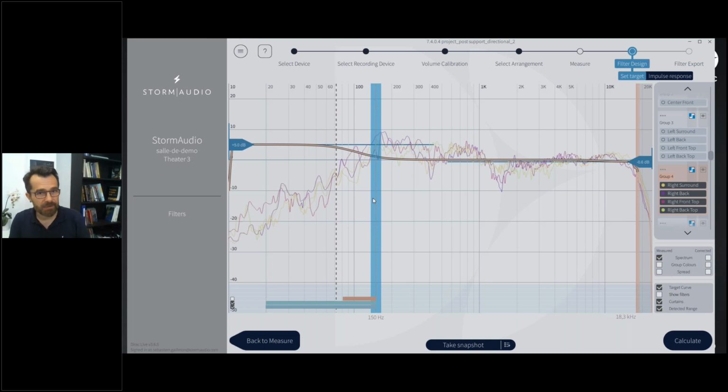But it can also create a very nice result by keeping the bass that is coming from the side speakers on the sidewall. Especially with new codecs like Dolby Atmos, you will get a lot of low frequency content coming from there, not only because of the LFE, but also because those speakers are playing down to 20 Hz. So by creating this localized bass management, you help keep the bass on that side, and that's great.